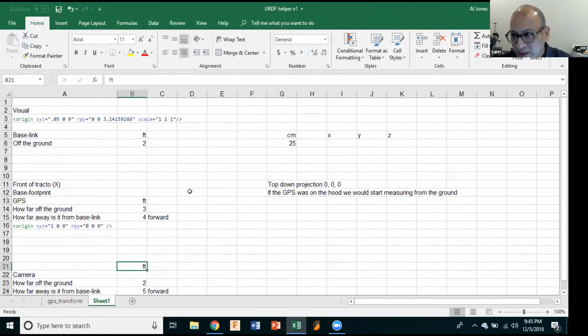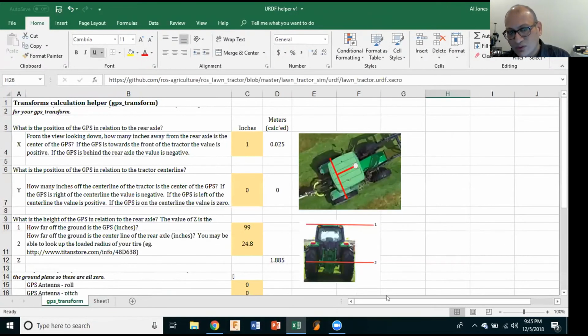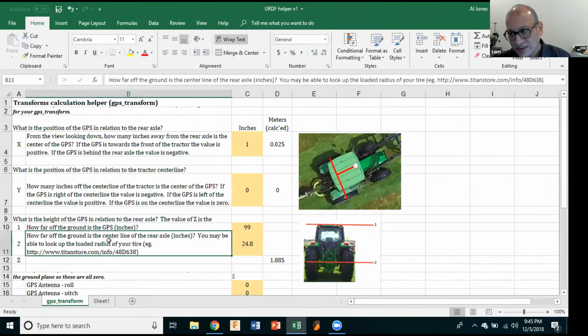Meaning, in other words, where the center of mass is located for that link. And this origin that you're showing me, when you define it under the link, is not the distance that you want from anything. That's just the link's own center of mass where it is located.